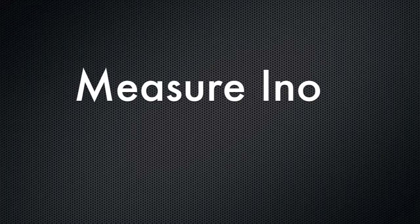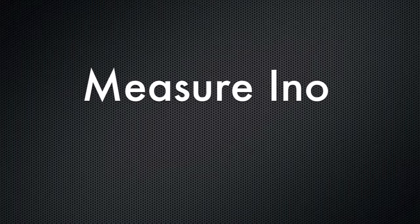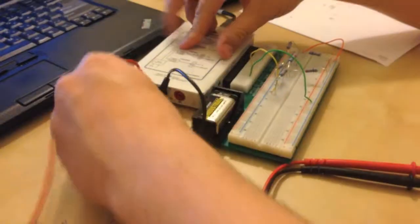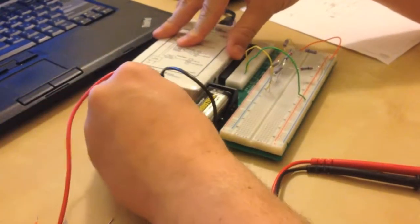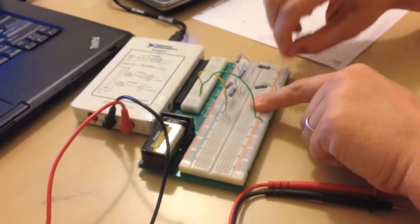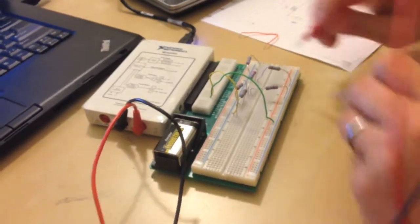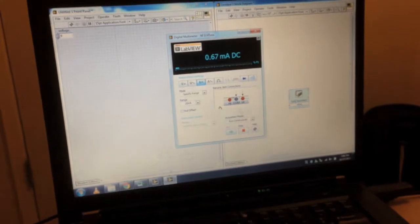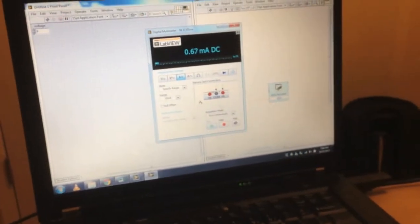Dividing my voltage by the resistance, I get about 0.6667 milliamps, but I'm going to measure it just to see how close it really is. So when measuring current with a DMM, I need to put the probe into the current slot just to make sure I do it correctly. I'm going to measure the current running through where the load resistor would be. And by doing this, I get 0.67 milliamps, so it agrees with my calculated value.